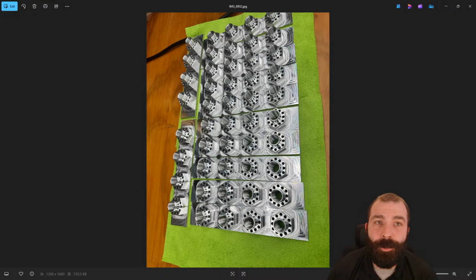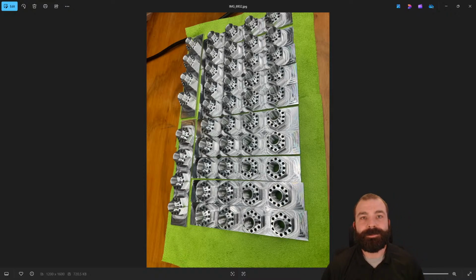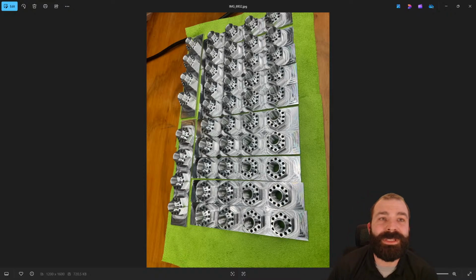Stuart, great point. Piece of copper shim always helps. I do notice, though, Stuart, in that case, when you start to use copper shims on things, your part starts to shift. So unless you're probing every single one, you could get in some trouble.